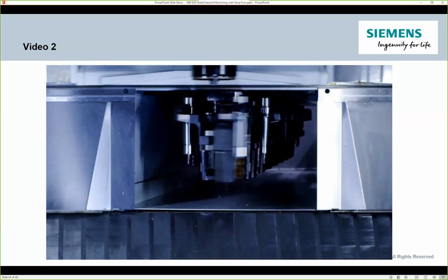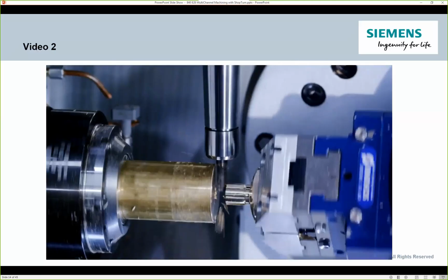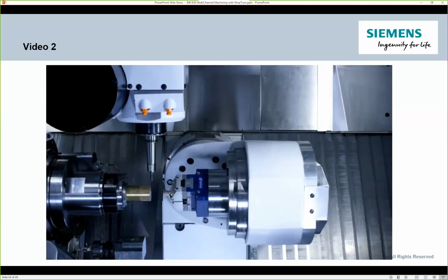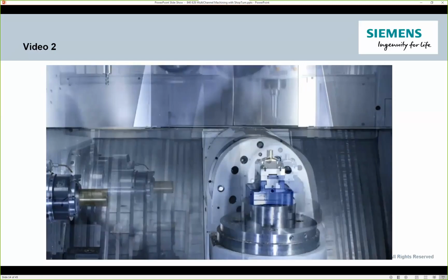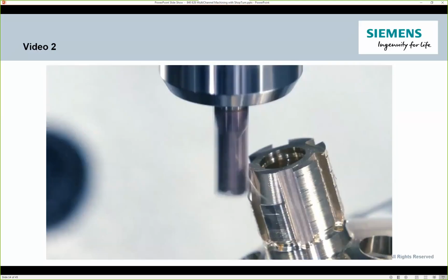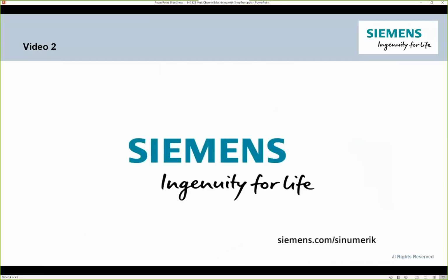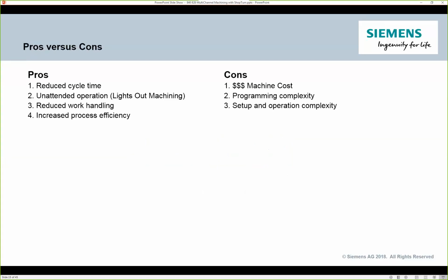So here I can jump around and do milling operations on my turning spindle, or transfer the part over into more of our traditional trunnion style kinematic and get into more 4+1 or 5-axis machining operations. Generally speaking, you're going to fit the machine tool a little more to your application. If you're a job shop and you want something more versatile, you're probably going to look at that traditional upper turret, lower turret configuration. I would say it's probably the most adaptable to any standard machining processes.